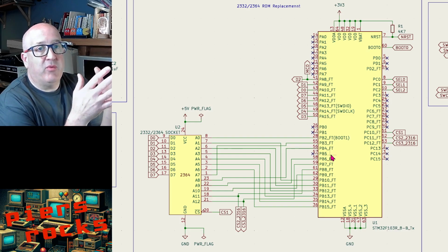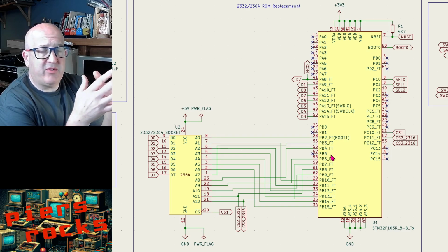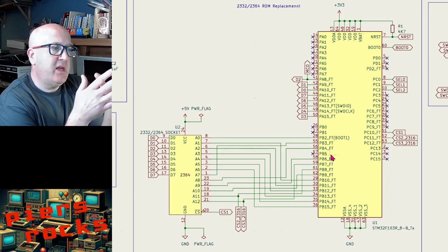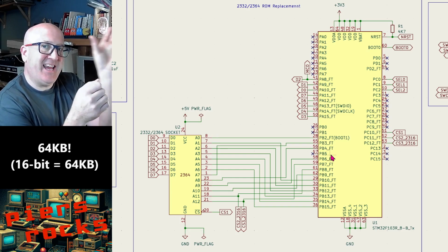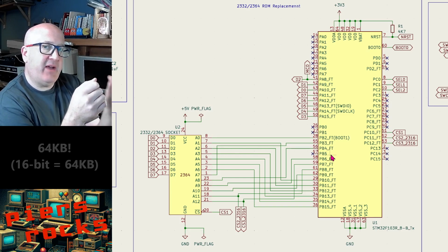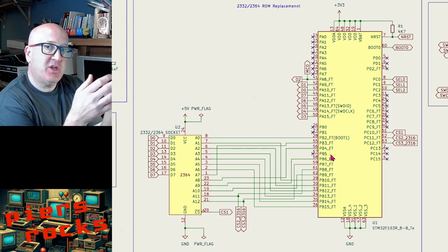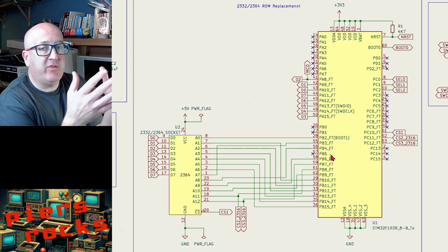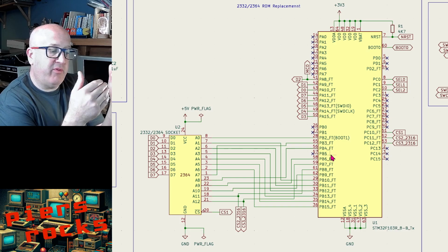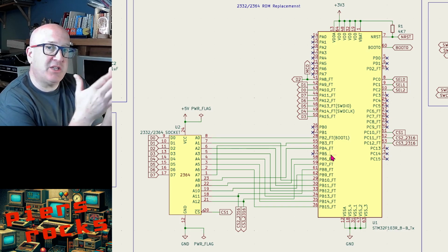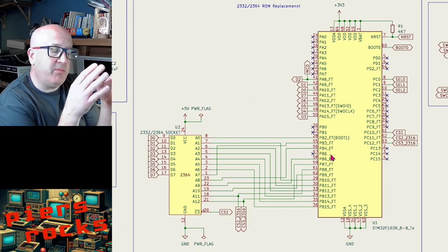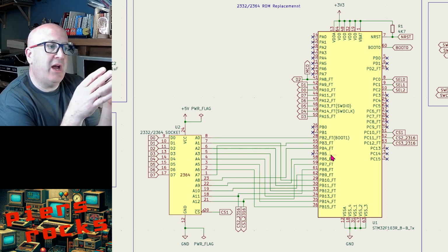The STM32F4 series has quite a small amount of RAM. I think it's 20K for the F103, and I couldn't fit a 16K image in RAM, so I'd have to use that offset of flash. And when you're running at high clock speeds on any of these microcontrollers, you have flash wait states, so that's extra cycles that the CPU is waiting for the flash to respond when it queries information. And things like caches and prefetches don't help you there when you're doing random access of flash memory, so you really want to keep your lookups from RAM if at all possible.